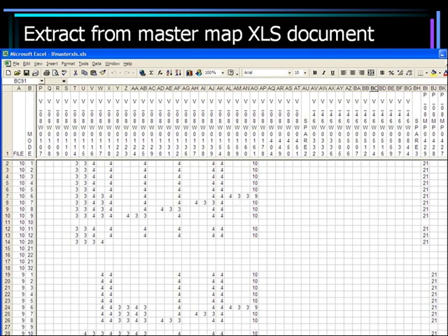So you can see that, just to explain, on column 2 there, that's a transfer from tank 10 to tank 1. So the mode is 1, so you're transferring from tank 10 to tank 1. The mode column there also defines the actual mode steps, so that each tank can have several different modes. We've got transfer to any other tank, and that's why the line that's got 10 and 10 there, which is transferred to itself, we call that a special mode called recycle rather than transfer to itself, and that's why that one's empty, because it's not actually a valid mode.